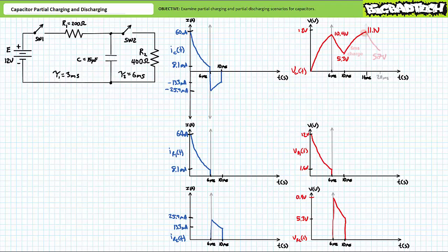11.1 volts. If we began another 4 millisecond partial discharge from this new higher state of charge, we might see the capacitor obtain a higher final voltage at the end of the partial discharge. Again, skipping the tedious math, another 4 millisecond partial discharge would result in the capacitor achieving a final voltage of approximately 5.7 volts. The observant among you will note that the second cycle resulted in slightly higher voltage values than the first. This being said, I'll caution you against making any premature conclusions about this upward creep.